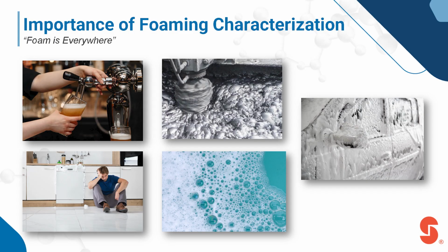Sometimes that's good. For example, for a vehicle care product, I want to get good coverage, and I want to make sure my customer is indulged enough to get that visual affection. Sometimes the foam itself is very beneficial for froth flotation. I can get the separation of my mineral by using the foam. However, if I have an application that requires surface activity as well as low foaming, that's quite challenging because a surfactant inevitably provides some foam property in the formulation.